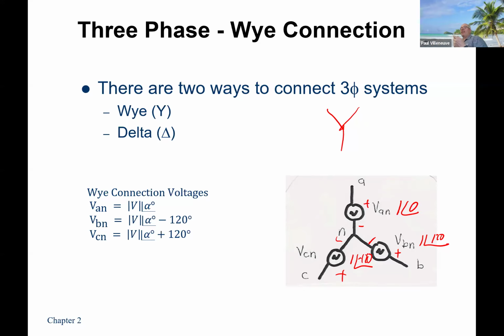The reason I'm telling you that is because I've had previous students in the past who said, we want to build a three-phase power system. We want to grab the function generators in the lab downstairs and connect them with their negatives together and build a three-phase power machine. No, it doesn't work that way because you don't introduce the phase shift. If you actually want to do that, you have to build something that builds in a 120-degree phase shift, which means you need power electronics.